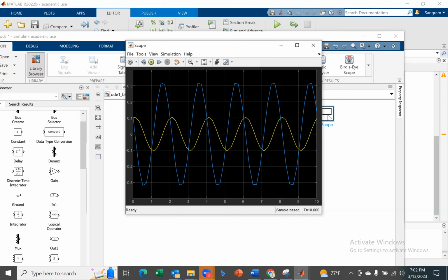Now, this may look complicated, but please try to understand. We have done all this. Remember the MATLAB scripts we wrote to find out the forward kinematics? Remember the MATLAB scripts that we wrote to find out the velocity of the end effector? To that same script, we are going to append this Euler-Lagrange equation, which means your robot will be solved from start to end in one shot. Everyone understood this? So now I'm going to write down the steps for analyzing the robot.